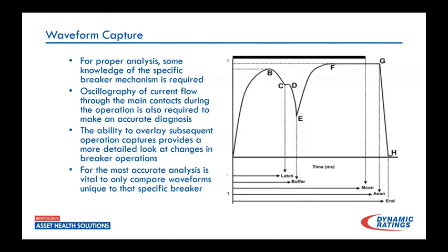And then the ability to overlay these operations. That was the trick when first stress testing, when we were in the field doing first trip tests. You always want to be able to compare. So we'll take that initial operation. The breaker's been sitting static for a long period of time. We'll operate. We get a capture. We'll close. We operate immediately again, and then we want to be able to overlay those. And we're looking for any small changes.